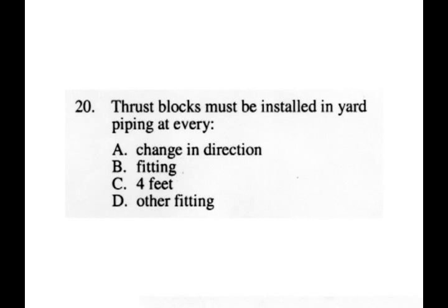Number 20, thrust blocks must be installed in yard piping at every... and the correct answer is change in direction. This dampens the pipe movement with sudden change of pressure. So with every change of direction, pop in a thrust block, letter A.